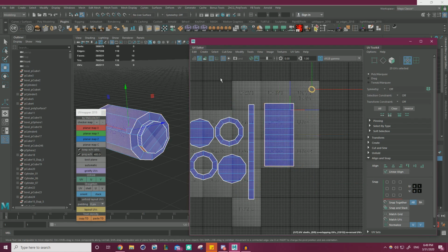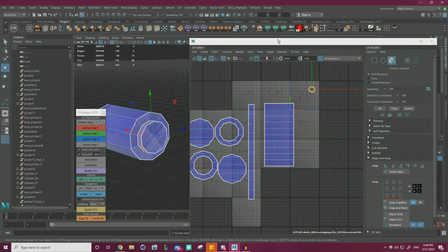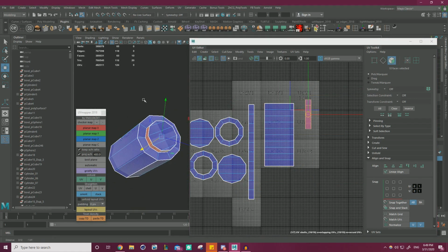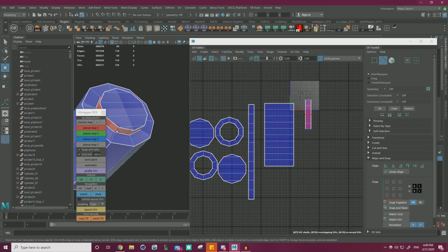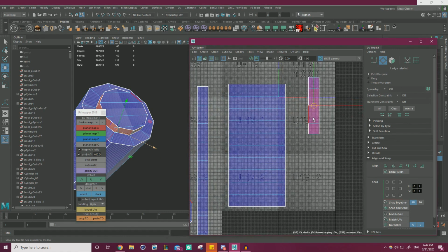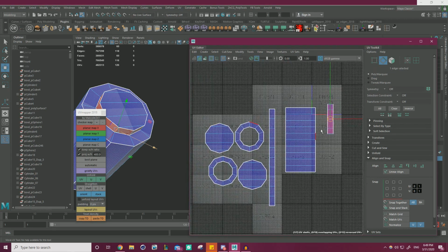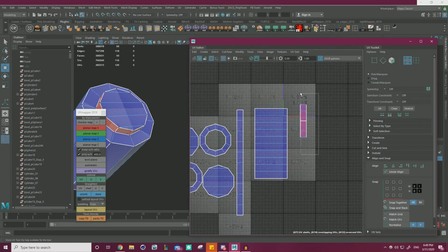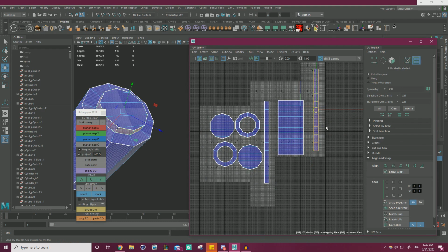And then finally this one, we can planar map from Y, add our cut to the bottom so it's hidden. And as you can see, it's purple. It just means that there's properly orientated polygons, which are these blue ones, and poorly orientated ones, which are red, on top of each other. But anyways, that should do it for these.